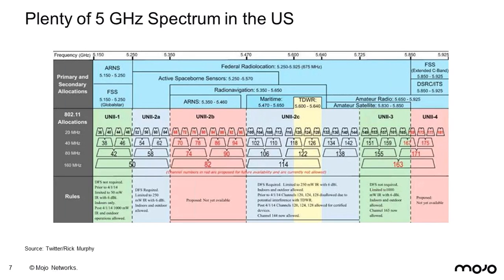So if we look here at the 80 megahertz channels, we're going to end up with another 3 80 megahertz channels because we already have this 165 here. So if you go out to UNII-4, that'll make up another. So we'll get 3 additional. But without that pink, soon to be available, hopefully, if we just look at all the others, we have the gray and the yellow.